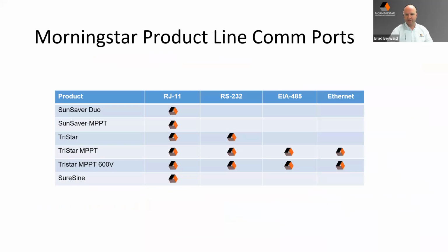So since the topic was some of the communications options, this is just a quick graph to show we have our standard proprietary RJ11 connection called Morningstar Meter Bus, and that allows some communication between the meter, and also can then be used to communicate with serial communications as well with various adapters that we make available.